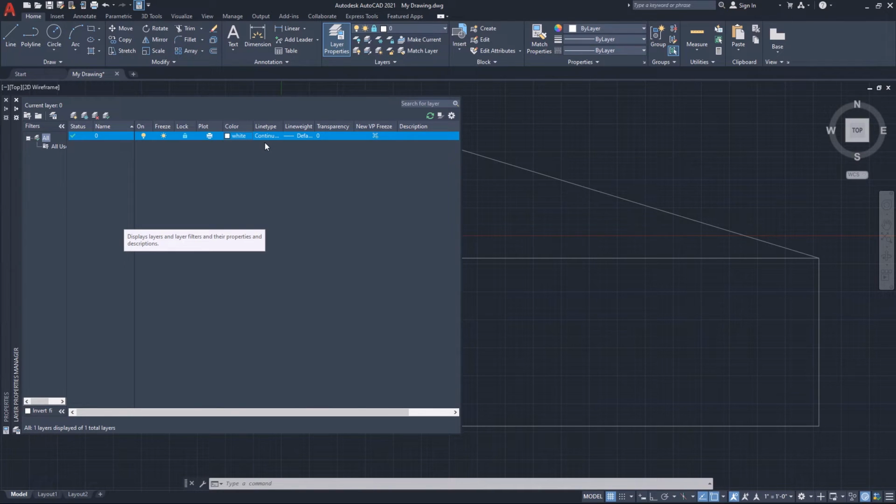The next column to the right is titled Line Weight. Line weight is critical to creating meaningful drawings. Depending on the plot style configuration being used to send the drawing data to the output printer, a subject we will get to in our next video, defining line weights to layers here can be very important or irrelevant.